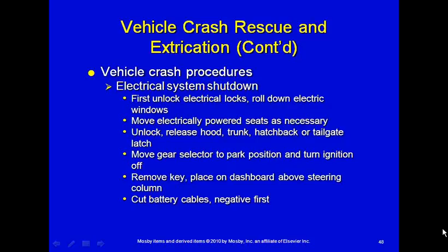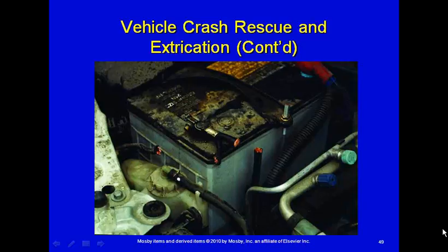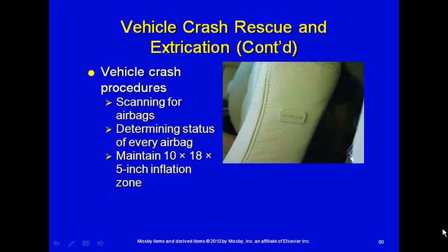Then we turn the ignition off, put the key up on the dash, and cut the battery cables, negative first. Here they're showing cutting a piece out of the negative cable, rather than trying to just unscrew the negative cable from the post. Just cut a chunk out of there so that the cables can't touch each other and potentially cause a spark.